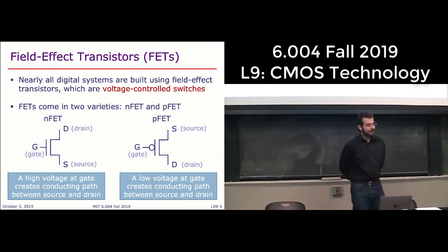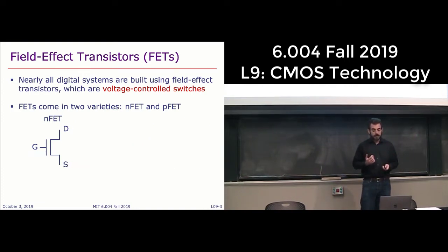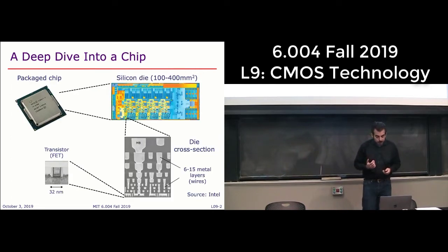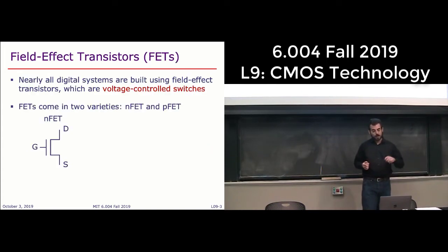So the reason there's no difference in the circuit diagram between the drain and the source is that how we name these 2 terminals, drain and source, is just a convention. Okay? These terminals are physically identical. This device is symmetric. If we go back to this picture over here, this is the gate, and we'll see this in a little bit more detail later. This is the source and this is the drain, but really there's no difference between both. I could call the drain the source and the source the drain.